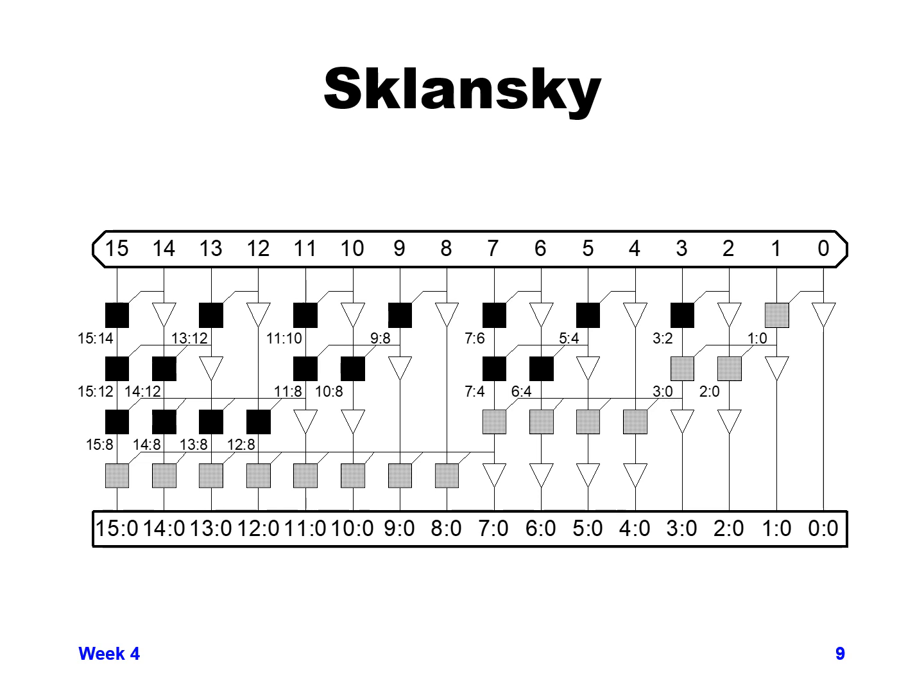So you can see fewer total stages of delay, but the larger your adder is, the more stages you have to drive for the higher order bits, and so it can slow down the critical path by quite a bit just based on the large amount of fan out. So that could be problematic depending on all the other trade-offs you're making in your design.